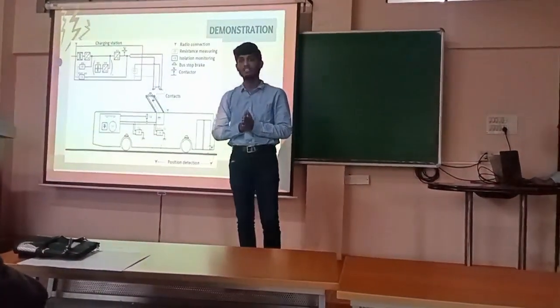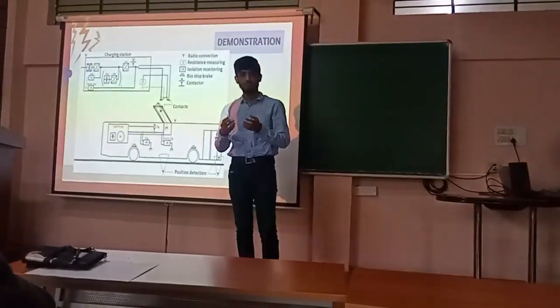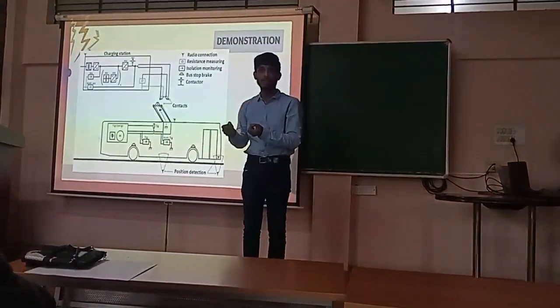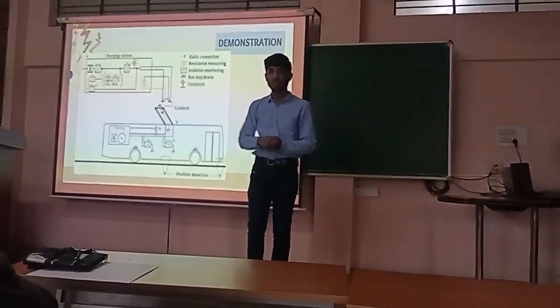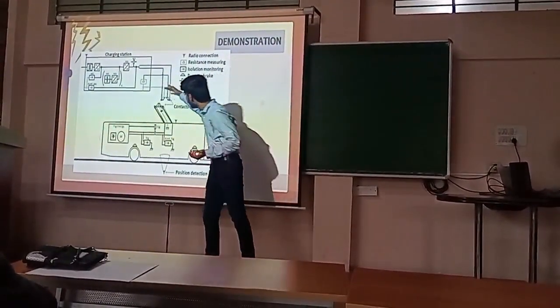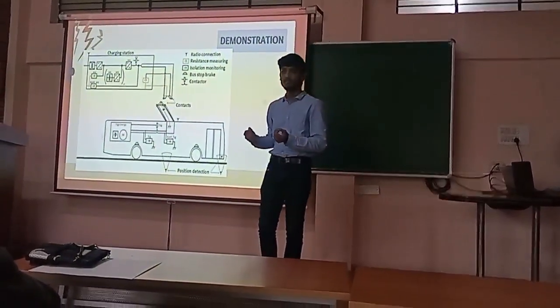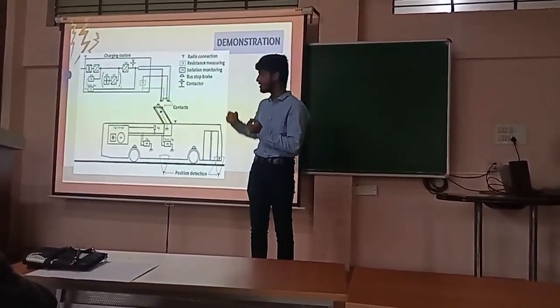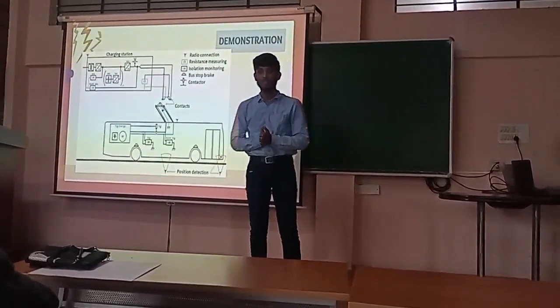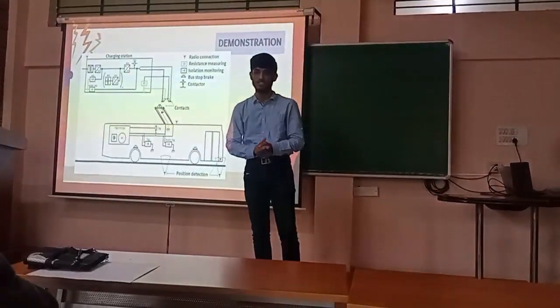Then the fast charging system will be totally powered up, so that it is ready to charge the upcoming bus. Then the pantograph deploys onto the bus. The bus guide rails act as charging rails, so that 350 kilowatts of DC power is sent straight into our ultra-capacitor battery stack.